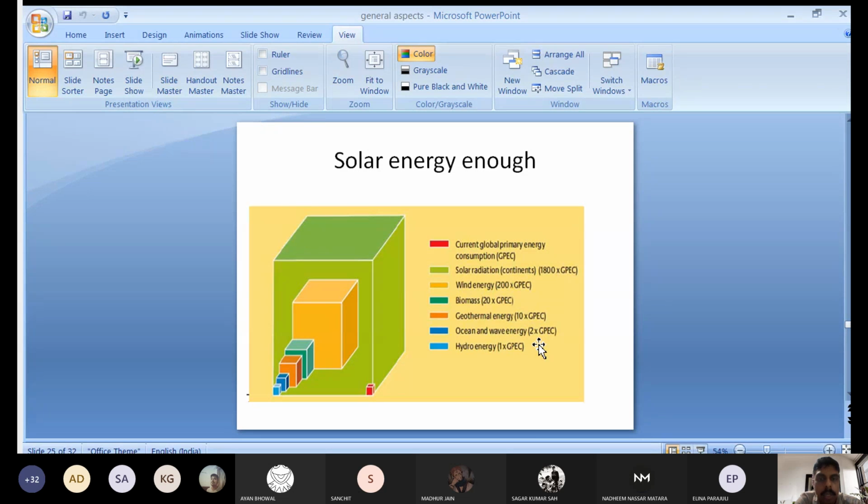What about PV? PV is also very diffuse. Actual efficiency is 10%, 13%, right? So if you want 3 kilowatts, how much area would you need? Maybe 20 square meters or 50 square meters. So in a car, there is not enough space for that much panel. And also it is intermittent in nature. If you are getting some power this time, next time you are not.